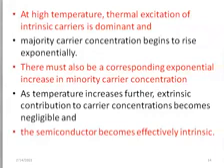So in this case, you find that the majority carrier concentration will begin to increase exponentially. And if this continues, you find a point where this temperature will make the extrinsic or the external impurities we introduce negligible, because the more the temperature, the more the breakage of bonds, so that the minority and the majority will tend to be equal to one another. So when the temperature goes beyond that limit, it becomes effectively intrinsic, because the effect of the dopant, that's the impurity, is not noticed very much.